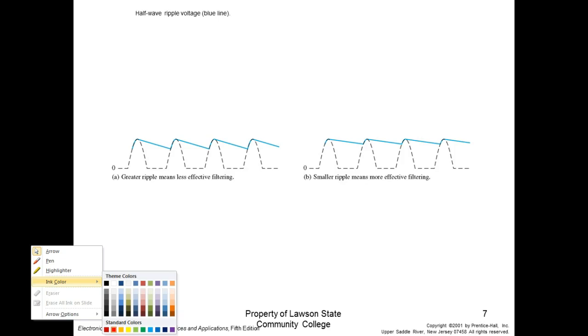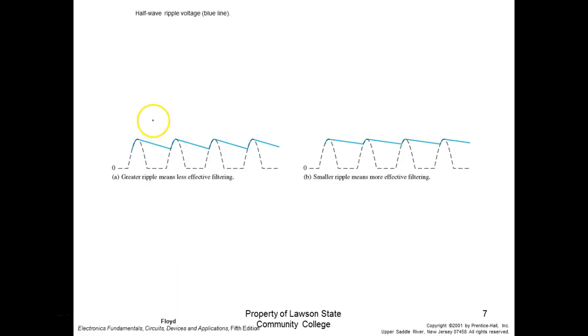You understand? So this is one of the things a switching power supply does, is it comes up and re-oscillates it at a lot higher frequency, like 50K. And now my capacitors can be what? Small, because they don't have to run the load for 8.3 milliseconds. If it's half wave, then that capacitor's got to run the load for 16.7 milliseconds. Because it's got to make it to the next alternation, right?